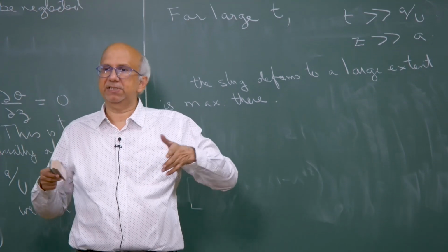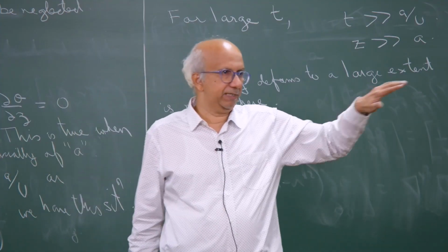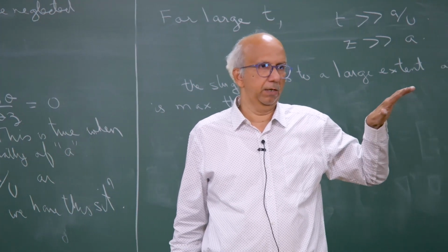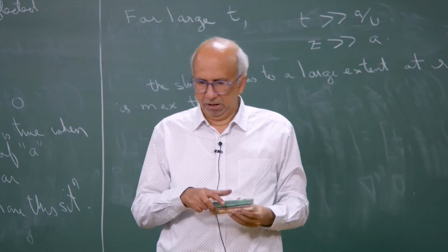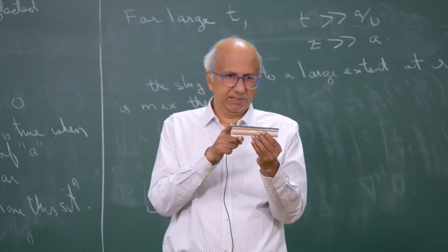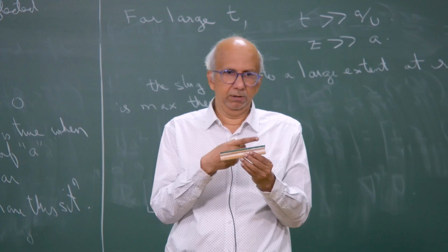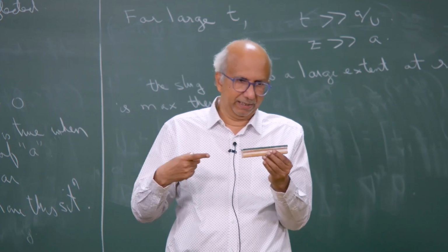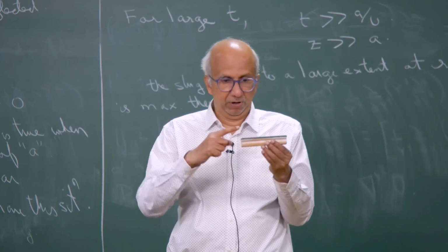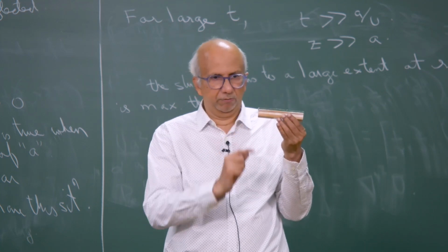So, if the distance in the axial direction is large, then in the axial direction the conduction will be slow. For example, if you have some temperature here and this distance is large, the conductive flux is going to be very low. The resistance is high because the length is high, whereas this distance is very small, so it will flow faster.